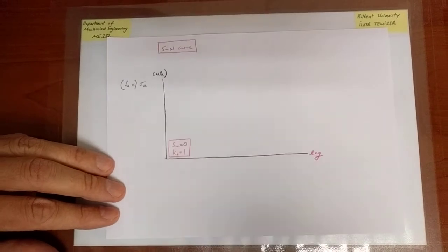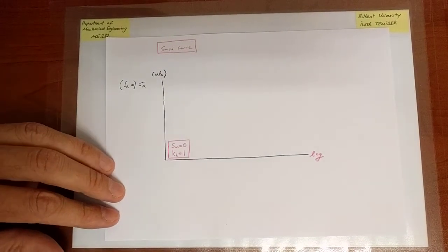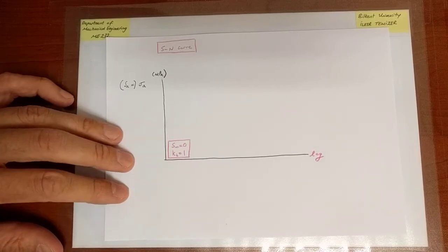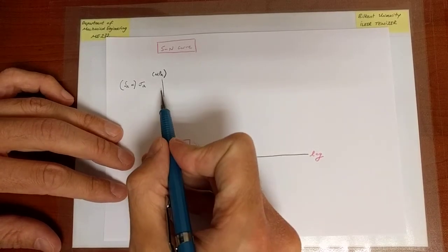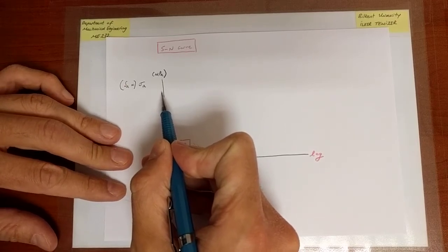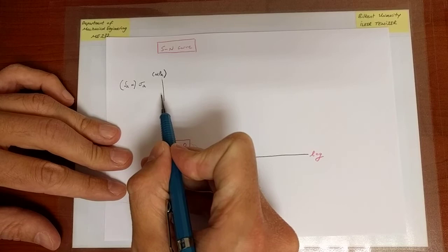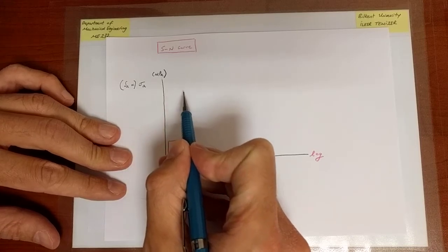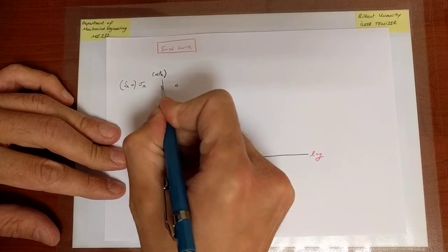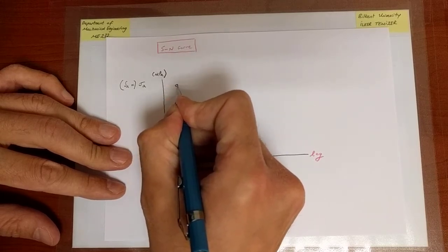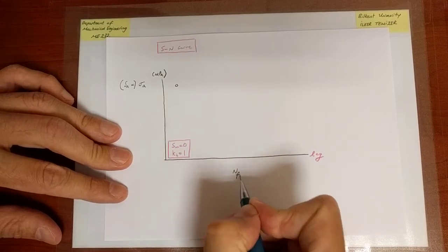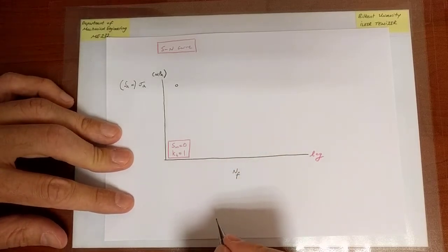Okay, so now let us depict the data. Well, what the data does is the following. First of all, you prescribe a certain stress amplitude, and then you start with a specimen, and then you just count the number of cycles until failure occurs. When failure occurs for a given stress amplitude, you have a certain number of cycles. So this is the number of cycles to failure, NF.